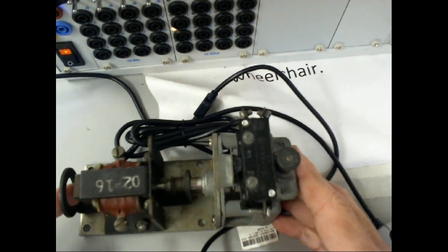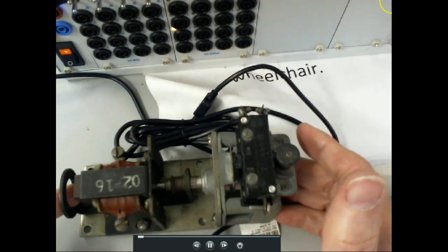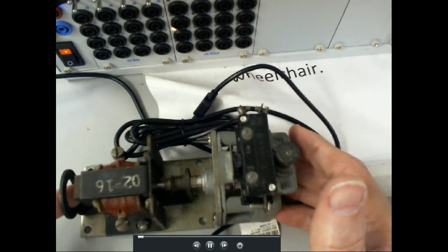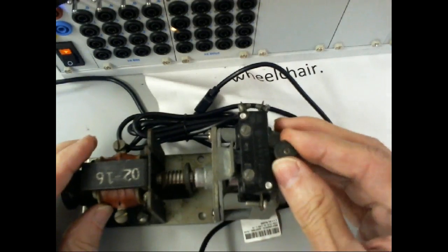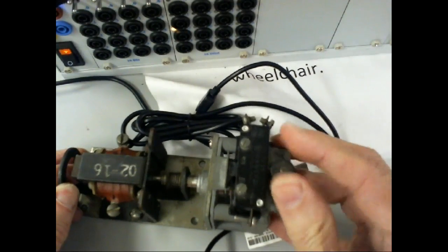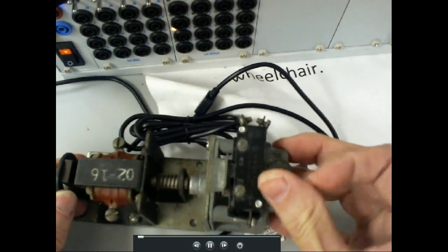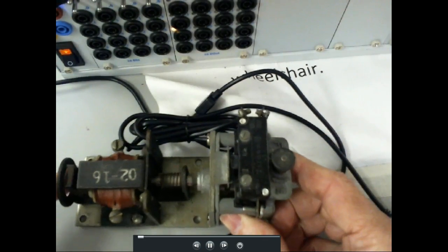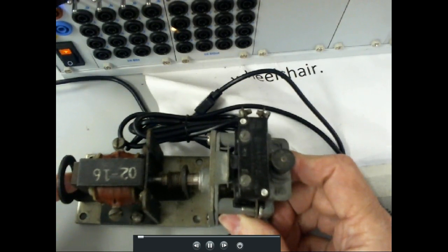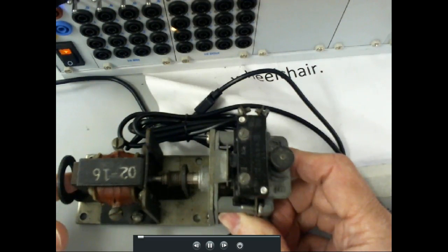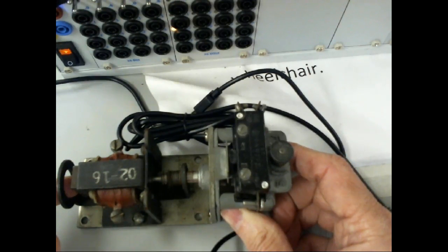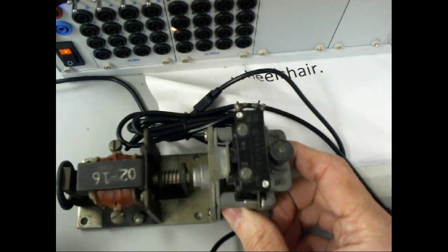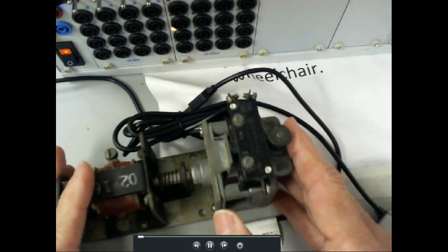So notice when I hit it, the contacts change instantly, right? You understand? But when I de-energize the relay, can you see it took time? Yeah, in fact. So what I just did is I'm increasing the time. So here, the contacts changed instantly, right? You understand? So a normally closed would open instantly, right? So this is why we say normally closed, timed closed. So it would go back closed after a certain amount of time, right? So this is an off delay timer.